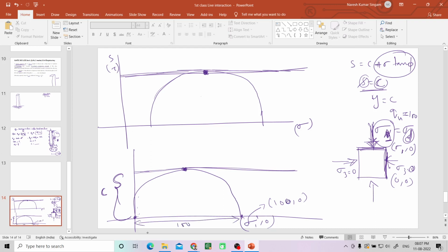what is the failure point? What is the C value here? It is half of the 100. Why is it half of the 100? Because it is the radius. The peak point is equal to the radius, and the diameter is 100, because it is passing through the origin and then reaching 100. And then C will be equal to 100 by 2 equal to 50. That is how you will take the value of C.